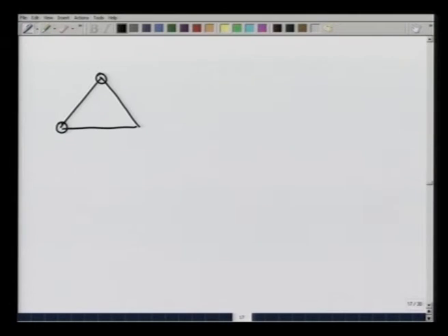So, let us see now, given a basic truss like this, which I just solved for, how can I make a bigger truss? Let us see, if I want to extend this further, I put a member here and give a joint here. This joint now has 3 members that can provide equilibrium. Then this point, suppose I do not want to provide a support here, I have to provide one more member, and I could provide a fixed support here, a fixed support here. That is one possible truss.